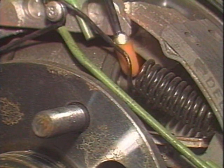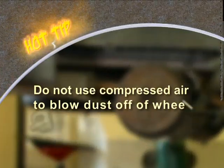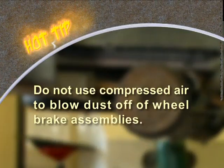If the boot is full of fluid, the wheel cylinder should be replaced. Do not use compressed air to blow brake dust off of wheel brake assemblies.